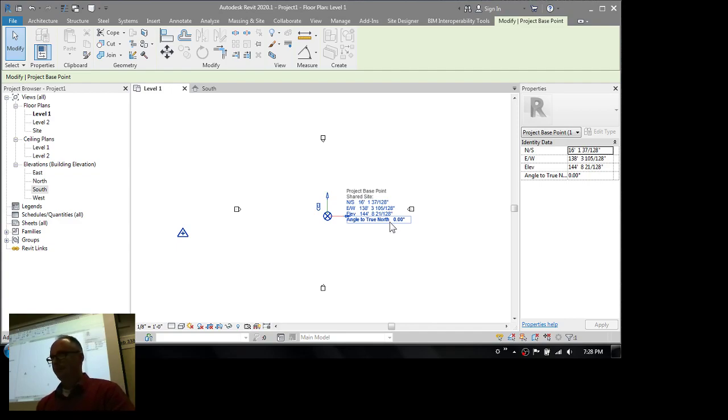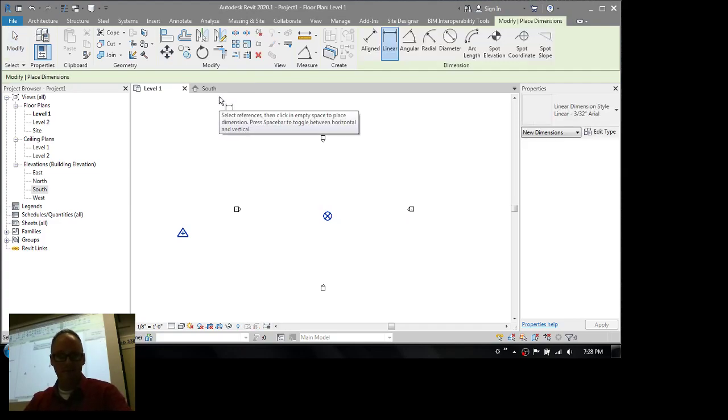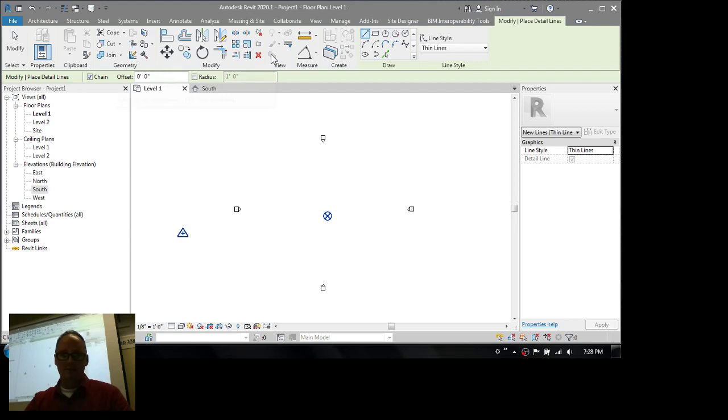Now, what I'm going to get you folks to do is wherever your survey point is right now, just go draw a detail line, so DL on your keyboard. And we're going to just draw a line here on an arbitrary angle.